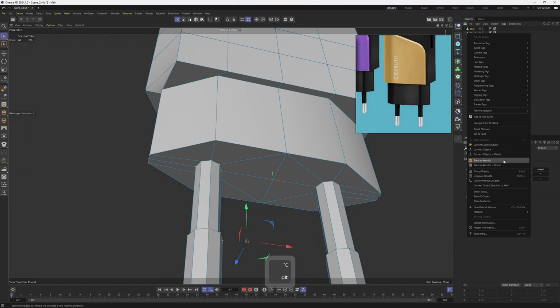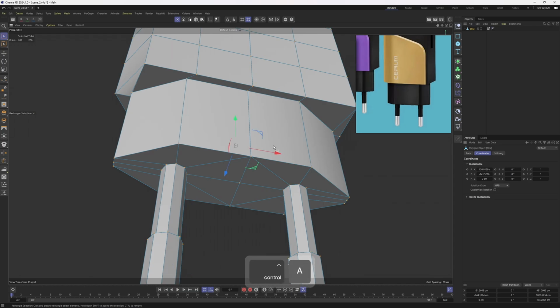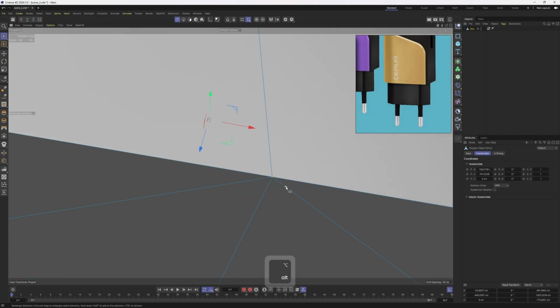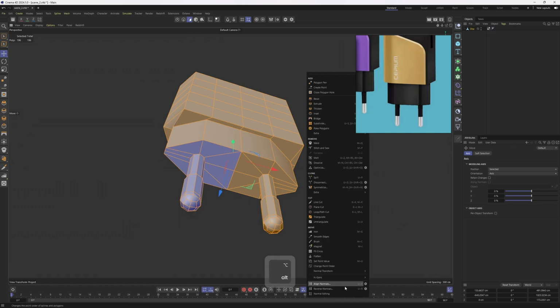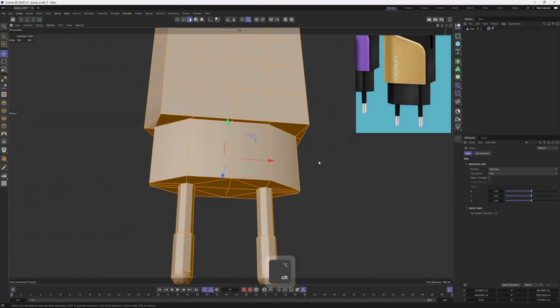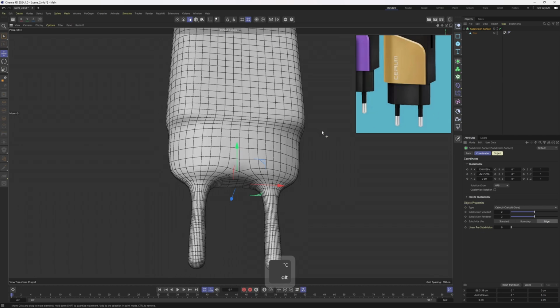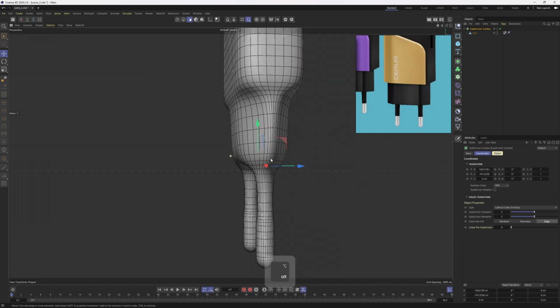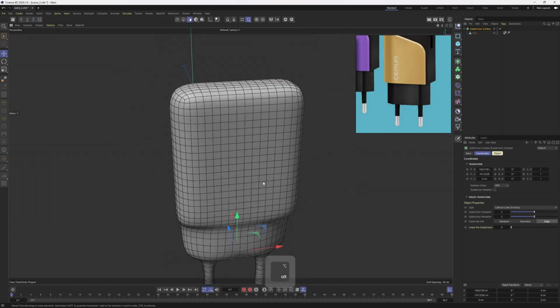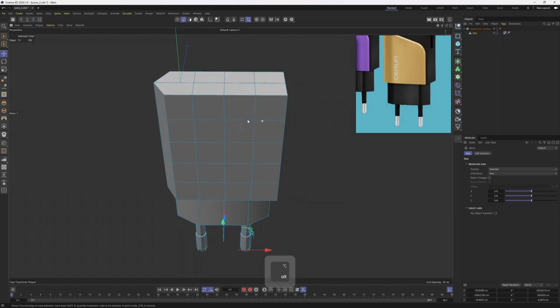Speaking of that, let's select all of these, click on connect objects and delete, select all the points, Ctrl A, and open up optimize options. I will increase the threshold because this is too low, set this to 1, and that should connect these points. That, as you can see, messed up the normals, so I will right click and click on align normals. I will put this one under a sub D again, and this time I will only check the wireframes, and everything is looking perfect. Now we need to add some weights to make the edges sharper, obviously.